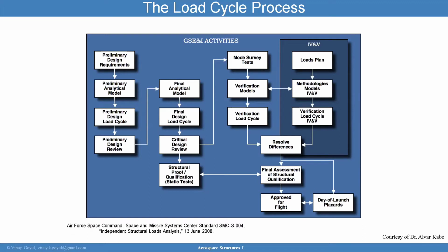If the launch vehicle and the payload are sufficiently robust, you can demonstrate that the reliability requirements for launch and flight loads, vehicle control, and performance can really be met without day of launch placard calculations. But you still have other constraints such as cloud cover, lightning, toxic constraints, and other things like that that could push the launch availability to be less than 100%.